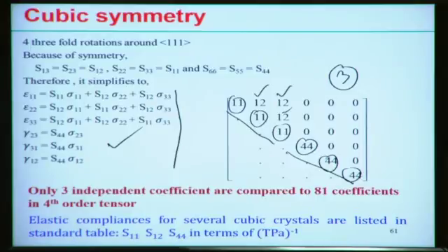With respect to the symmetric nature of the compliance or stiffness matrix, we can write the linear system of equations in terms of either stress or strain, and if we solve it, we can find the different constants. Or vice versa, if the constant values are available, we can use the different compliance or stiffness terms for a specific problem and correlate with respect to strain or stress.